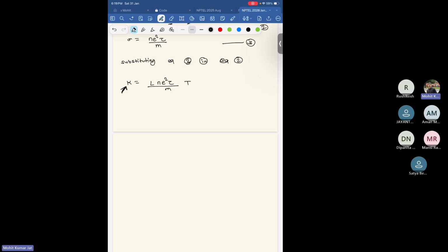If you have any system in which you can measure the conductivity, let's say you measure the resistance of a wire, and you know it's at room temperature, let's say 300 Kelvin. You measure its diameter and length, and its resistance with just a voltmeter and ammeter, and now you know the electrical conductivity.